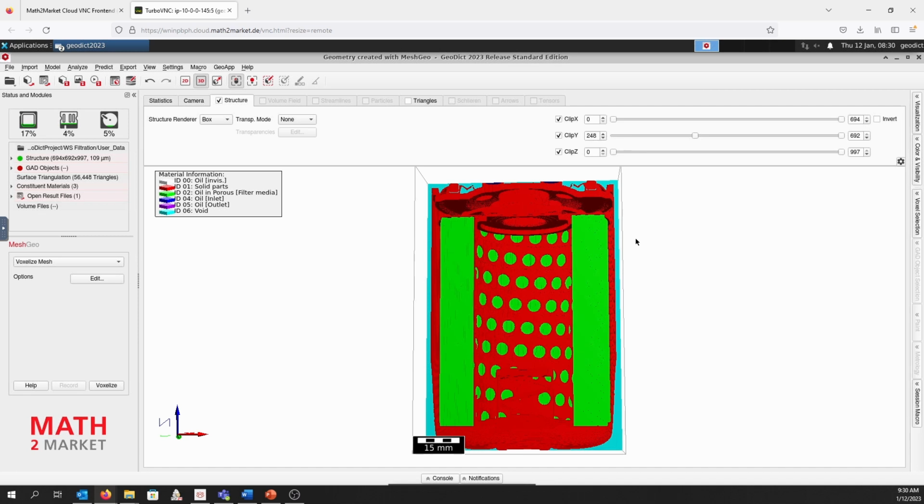So you need to have the original data valid, so that the original data gives more or less, for example, for complex complete filter media, the data and the shift in X, Y, and Z direction, because this is something we need to know from the original CAD data. The same holds for the pleat structure itself. So it's mostly the pleated structure, or the height of the tip, is somehow defined by the housing parts, which might also be flexible in your case, but mostly have defined height or size.